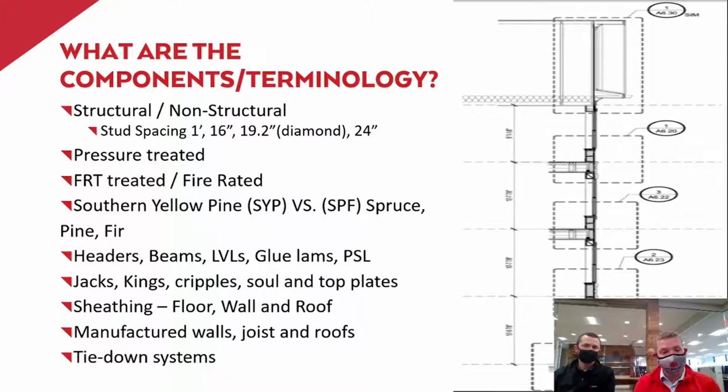A PSL is almost the exact same thing as an LVL, except it's in post form. And you'll see PSLs called out in a lot of corners of buildings, areas that receive a lot of roof load, or on either side of large openings, transferring load from above.